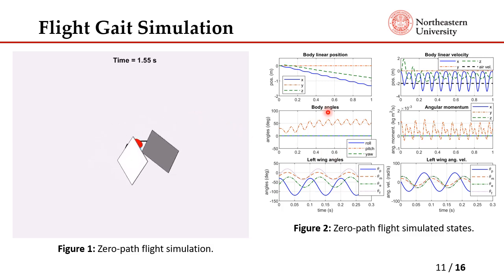And we have a limit cycle after 0.5 seconds, where it goes to a pitch angle of about 50 degrees. You can see it on the left over here. So there's this upright and almost horizontal flapping angle. This flapping trajectory is something that you typically see in hovering birds like hummingbirds.